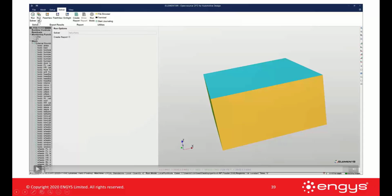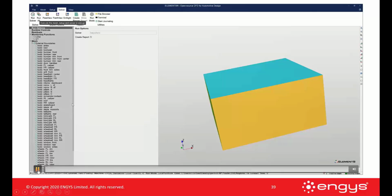And if I was connected with a client server connection to my HPC, it would literally kick off a meshing job. Then it would run a setup utility to set up all my boundary conditions. Then it would run the solver. Then it would run the reporting tool within Elements and generate a report automatically. So here, run all would execute mesh, setup, and solver in one go.